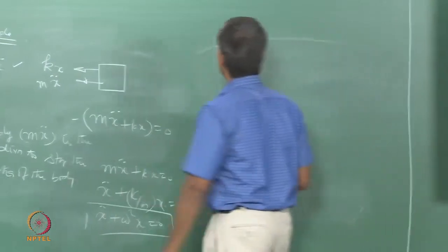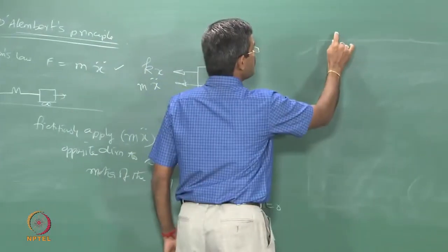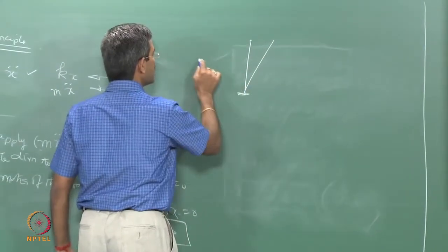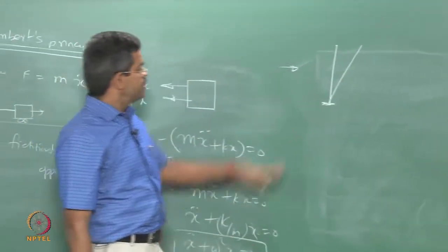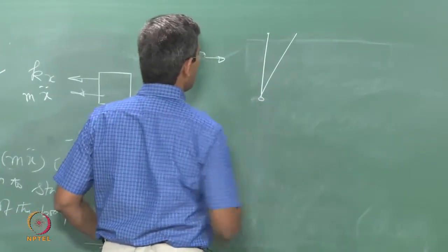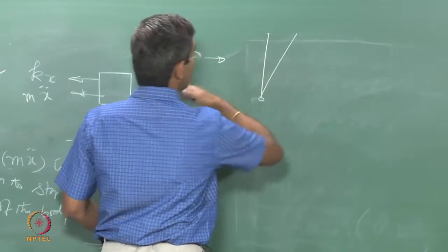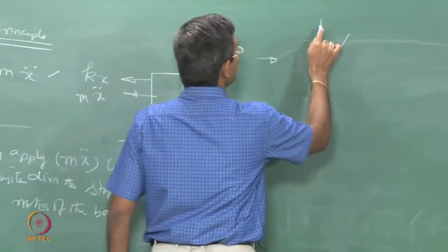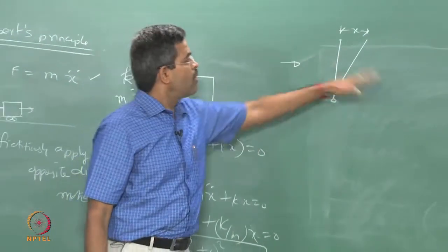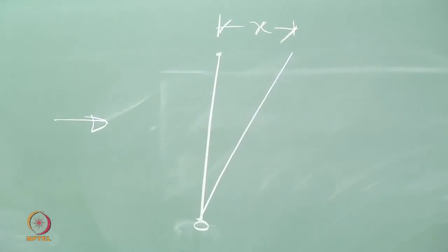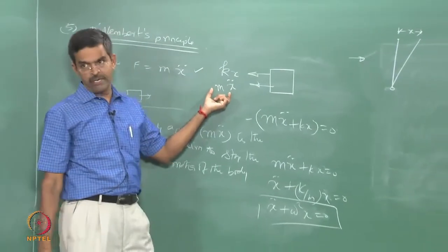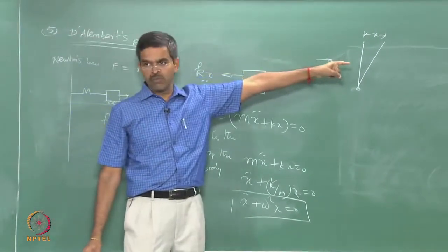Imagine there is a stick model which has got only 1 degree of displacement, which is the tip. Let us say under any force, this is hinged or fixed, whatever may be, because the shape may be varying, I will make it as hinged. If it is fixed, the shape will vary. So, it will oscillate like an inverted pendulum. There is only 1 degree of displacement which is allowed to this mass. So, when the mass is pushed to the right, it will oscillate and so on and so forth. Therefore, it is easy for you to apply a negative force which is proportional to its inertia in the direction opposite to the motion of the body.